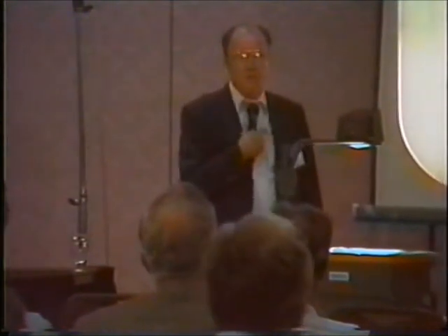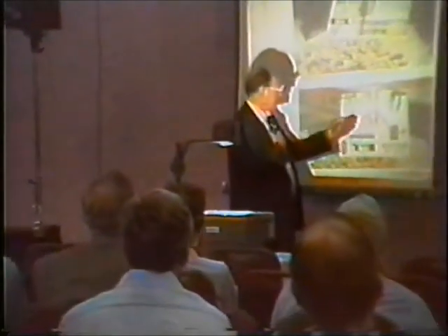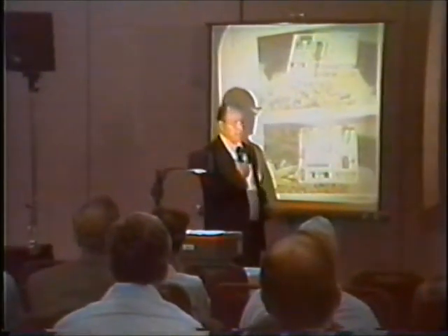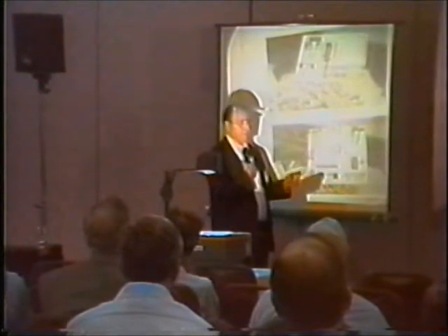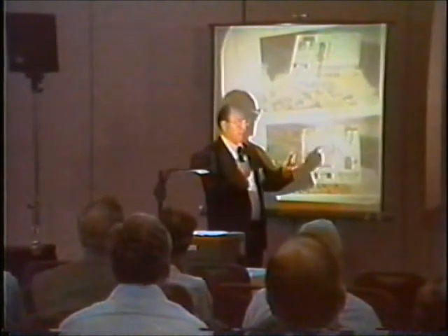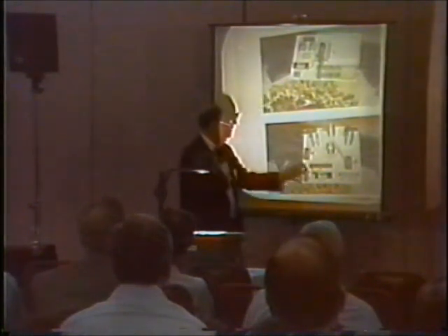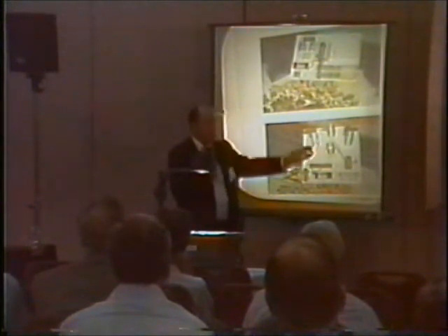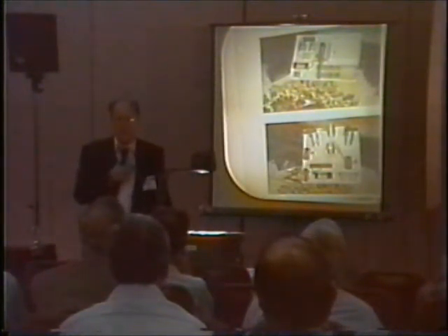And how you know when they're tuned or actually functioning: there's a little neon light that has one leg with a resistor, about a 47,000 ohm resistor on it, on one leg of the wire on this neon bulb, and then there's another leg that just sticks out like an antenna. When this thing is functioning properly, that bulb lights up. So you know immediately when it...